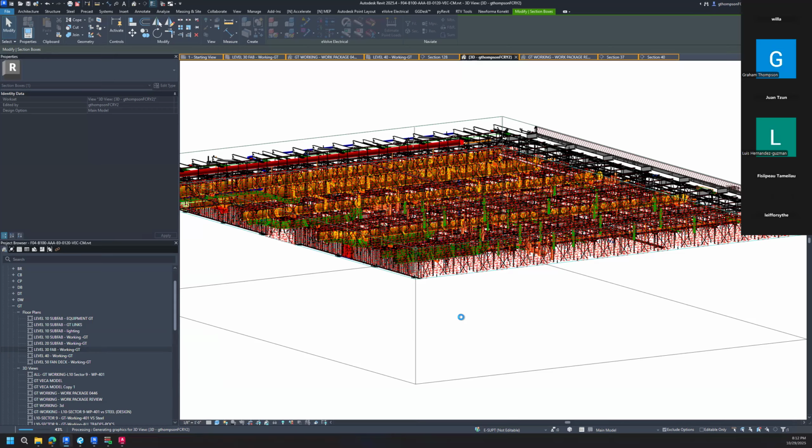On my side, we model it and then provide them a Trimble file, which essentially is a robotic total station that will shoot a laser and tell them exactly where to place something. That's how they place everything, and it's all placed within a 16th of an inch of what we model. So if they need it in a different location, we put it in a different location and send out a new Trimble file.